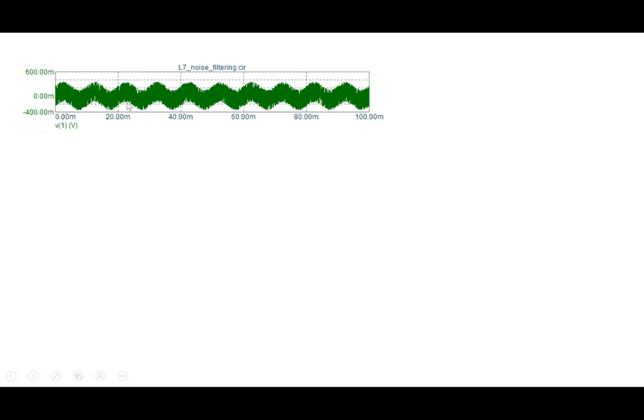Let's say this is through simulation. So let's say you have a noisy signal here. You can see these very sharp variations that you see here around noise, but you can also see that there is some periodic signal. There's a sinusoid here. So it's a periodic signal immersed in noise. So this is the signal. Now I can take a very simple circuit that you are familiar with, a simple resistive capacitive circuit here, an RC circuit. And I can apply this particular signal as an input, and then I look at the output.